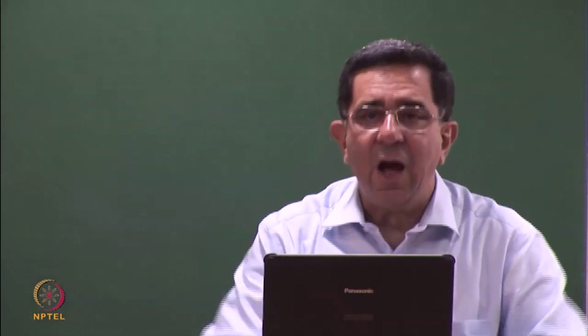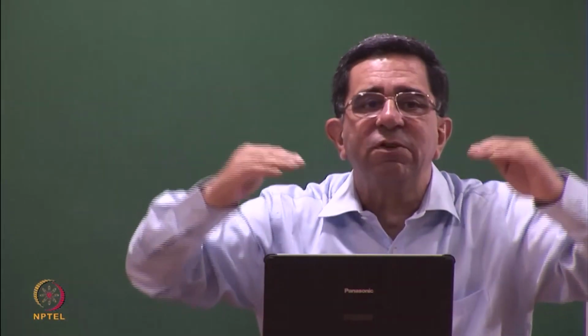Your footing, let us say, is at 1 meter depth. If you have done a good design, you will find the frost penetration depth and keep your footing below it. So maybe your frost penetration depth is 1.5 meters and you have kept your footing at 1.75 meters. Now if instead of the soil I can put a layer of tire chips, the frost penetration depth gets reduced, because this is a thermally better material in terms of preventing frost penetration. So they are used in the developed countries for reducing frost penetration.